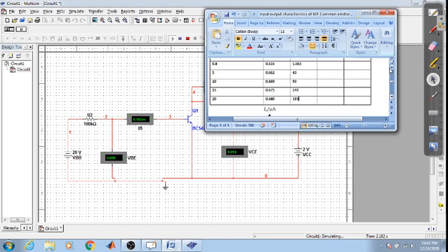So how do you plot that? So this is the graph. You take VBE along the x direction and IB along the y direction. So at 0 volts, at 0.1 volts, you have taken the readings here at 0.2, 0.4. So just take the x axis as VBE at 0, 0.2, 0.4, 0.6, 0.8, 1.